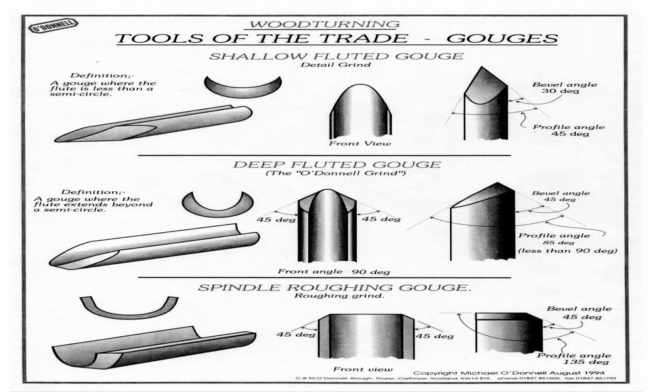And so I wouldn't spend a lot of time on that. I know a particular turner that says his bowl gouges have to have an angle of 41.5 degrees. And you ask him why, and he says because that's the angle of a beaver tooth. He says the beaver is the most effective in cutting down trees, and so that's the most effective angle. But really, he sets his tool rest at 45 degrees when he sharpens. So 41.5 degrees, it's not that critical. It's what you get used to doing.